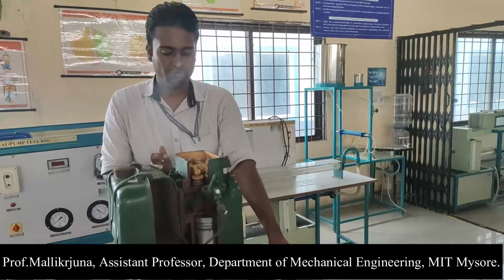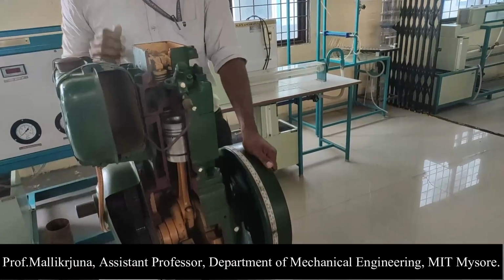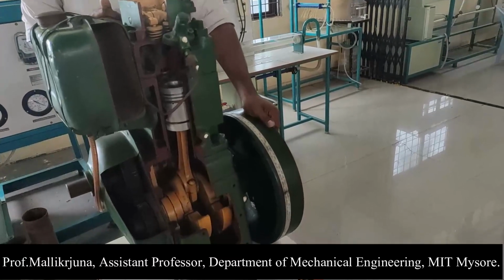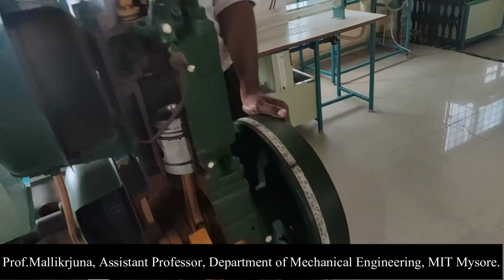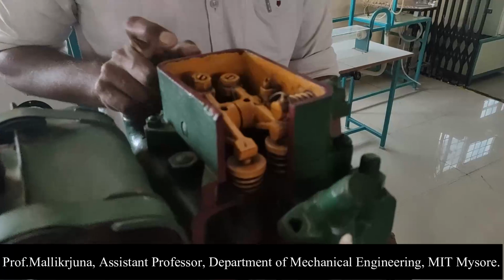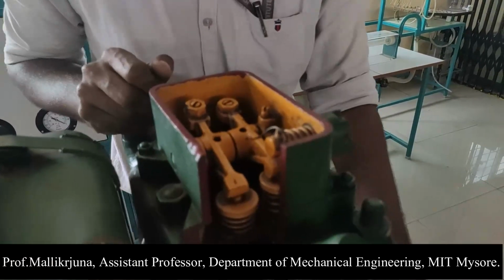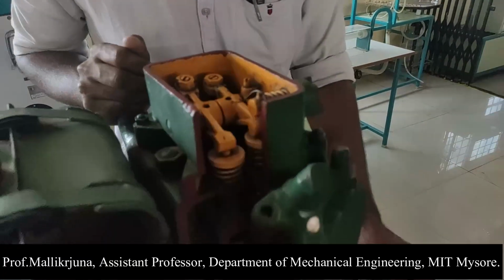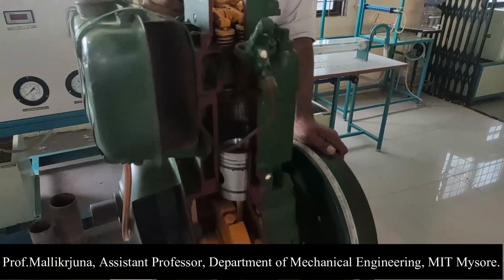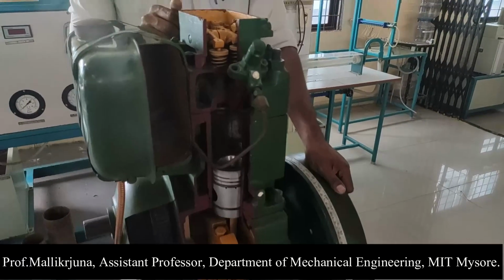I am giving the rotation manually. The piston is moving downwards, you can see over there. That means suction is happening. Here, if you observe, the inlet valve is opening. Inlet valve has a movement over here. You can see that. Now the piston is moving in an upward direction. Still the inlet valve is open.